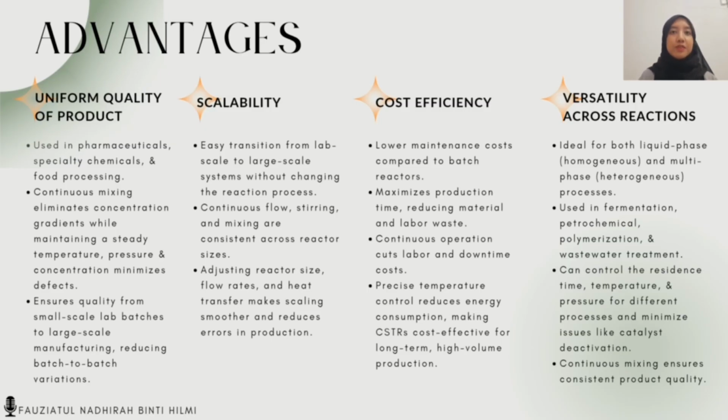The last one is versatility across reactions. The CSTR is ideal for both homogeneous and heterogeneous processes, where it is used in fermentation, petrochemical, polymerization, and wastewater treatment. This is because it can control the residence time, temperature, and pressure for different processes, minimize issues like catalyst deactivation, and ensure consistent product quality.